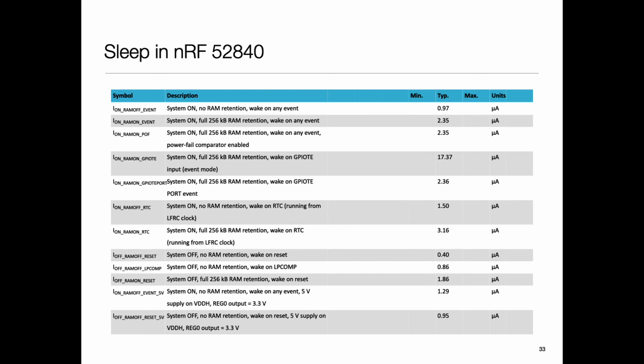Same, it's not just for processors, it's also for things like, let's say, a hard drive. Should the system put the hard drive to sleep or not? Right? I mean, if I spin down the hard drive, then when the request to read or write a byte comes, that disk needs to be spun up. During the time the disk is spinning up, it takes a higher current because it's working against friction. So many systems have the characteristic that during the wake up time, they may actually have a surge of current.